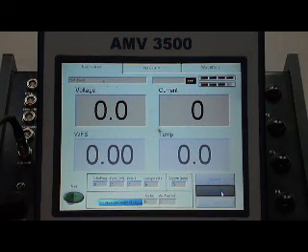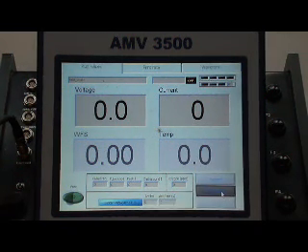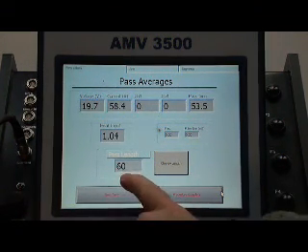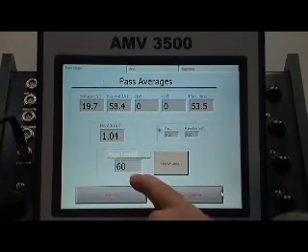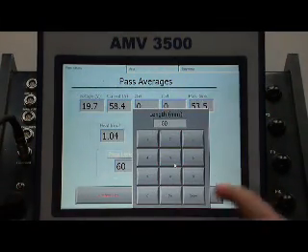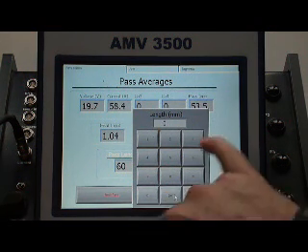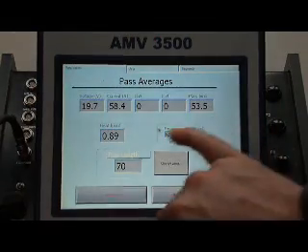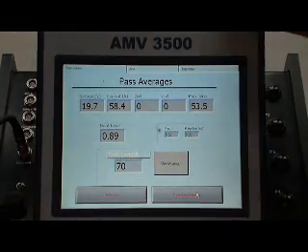Pass complete. And it's added the 3 segment lengths up to give us an overall pass length of 60 millimeters. We can change this if we want to. Supposing there was an extra 10 millimeters somewhere that we got wrong overall. So our overall heat input is changed.